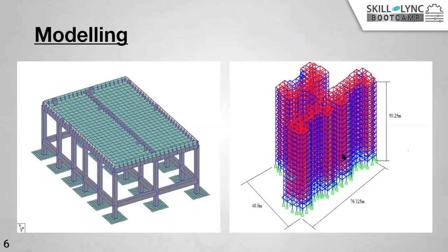Whereas in SAP and ETABS, we have to define the grid first. It will be easier then, because whenever we want, we can use the grid position as a reference point in SAP or ETABS, which will make you much quicker in modeling. If your grid positions are marked very clearly first, you will be able to position any number of columns very easily without any issue.